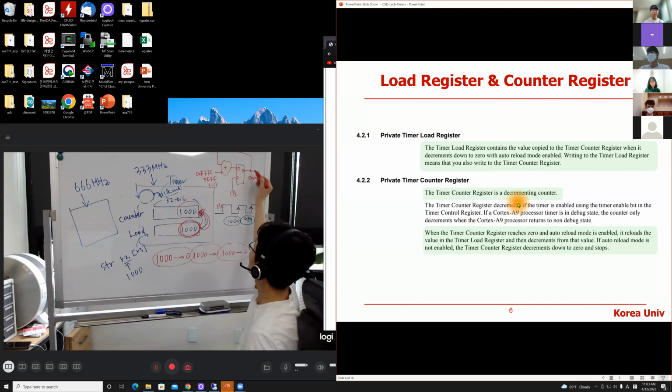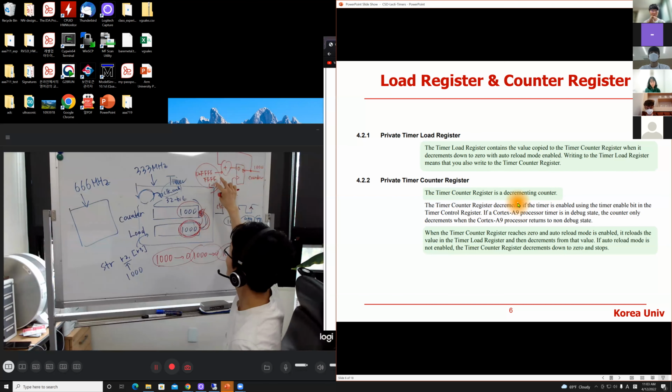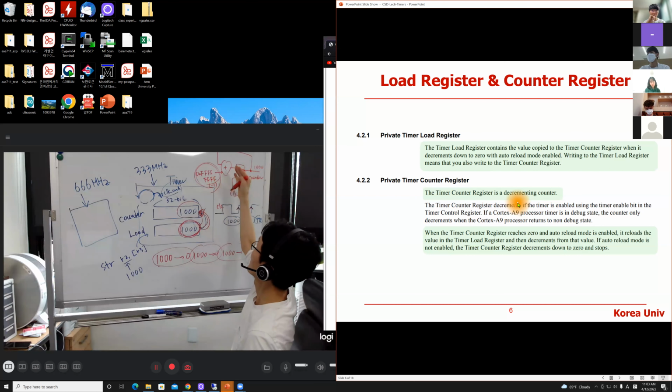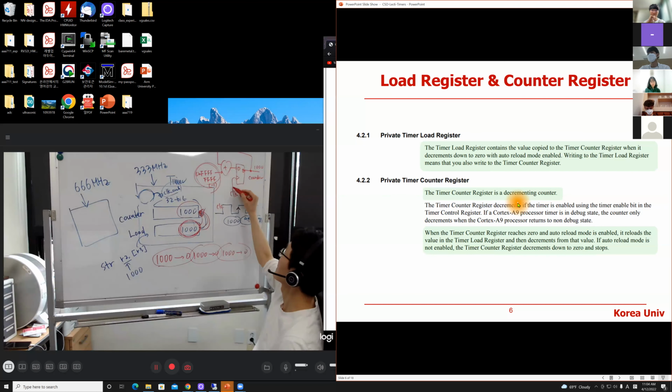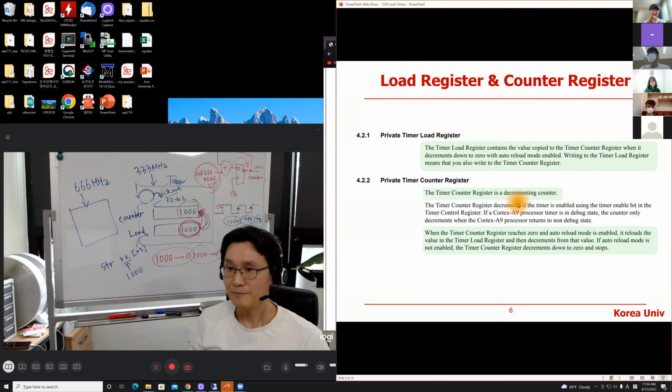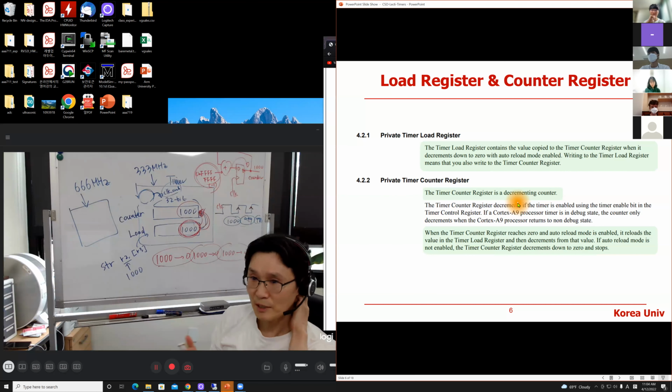So the value, starting from 1000, you are doing +1 plus this value plus this value, right? That is -1, so effectively you are doing a -1 operation. Then at the rising edge of the clock, it is taking a picture, right? The flip-flop is like a camera. So it's very simple hardware.